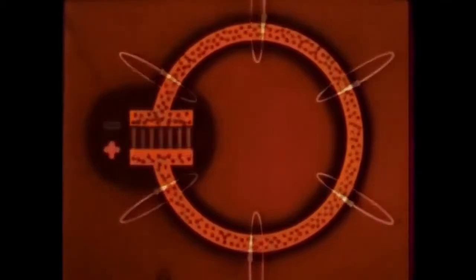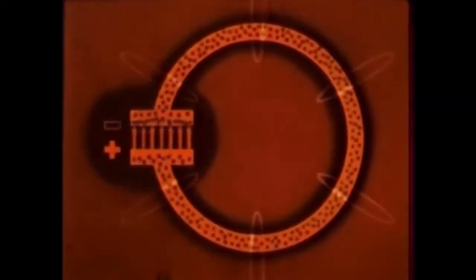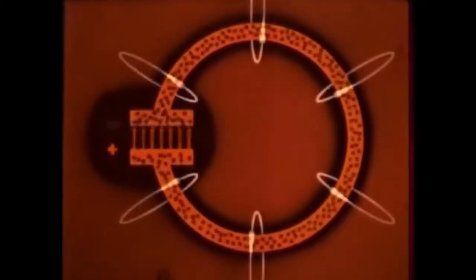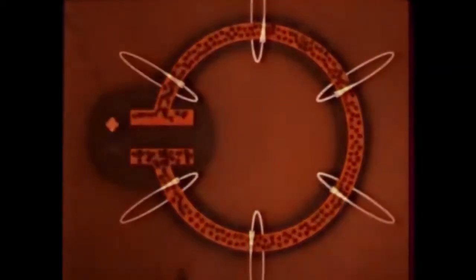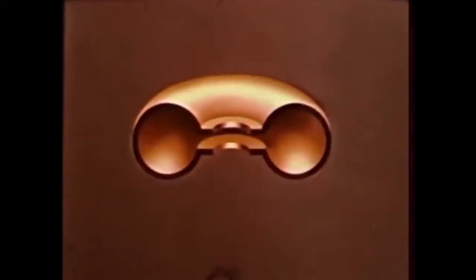The smaller the value of the capacitor and the inductivity of the loop, the higher the frequency of the oscillation, or the resonant frequency. With this simple circuit, a rather high frequency can be obtained, because the inductance of a single loop is very small. To obtain higher frequencies still, the inductance can be further reduced by placing 2 or more loops in parallel. This results finally in the formation of a closed resonator having certain very high resonant frequencies, which are determined by the dimensions and shape of the cavity.